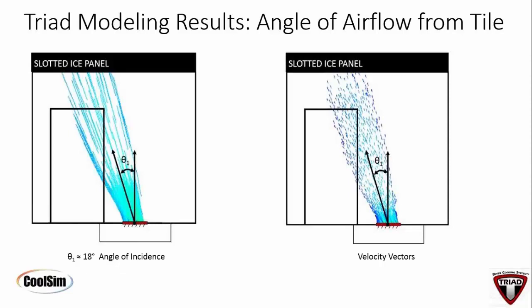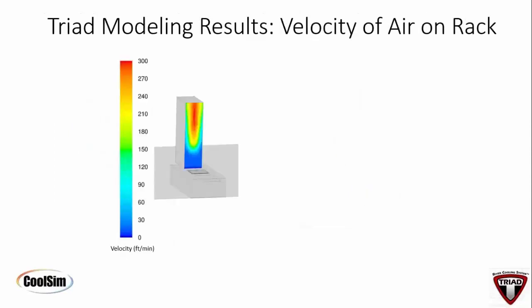Yeah, because you have eddies underneath that floor just being stirred up just simply from the pedestal understructure themselves or the stringers, which actually affects that movement of air. And so the design of the anterior fin was designed to work like an airplane wing. So there's lift and drag on both sides no matter what direction the air is coming from. Right. To give it a direction. That's the intent of it.